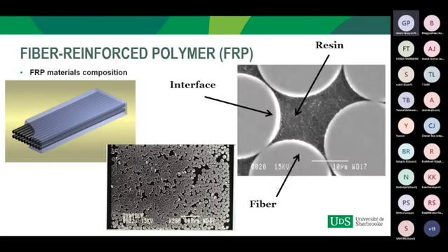The fiber reinforced polymer bars are made from composite materials, fiberglass and carbon fiber, and are manufactured by a pultrusion process using a mix of fibers and resin. You can see from this figure a microscopic view of the fiber reinforced polymer bar, where we can see the fibers and resin and their interfaces. Generally, the fiber content is more than 80% of the total volume.